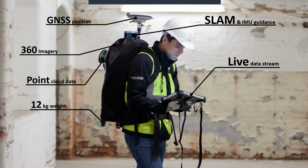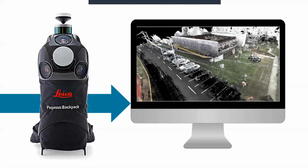We have narrow spaces, we have buildings, we have forts, we have uneven surfaces. And in all those cases, when we don't have vehicle access, we can use mobile mapping solutions like this, where we can mount it on our back. It'll be around 10 kg to 12 kg in weight, including the batteries, along with the additional tablet, where you can have a GNSS, which is an industry grade GPS rover, and have imagery as well as point cloud data. We can map the same way we were doing with the terrestrial laser scanner, by mobile mapping solution, and we can capture whole streets.